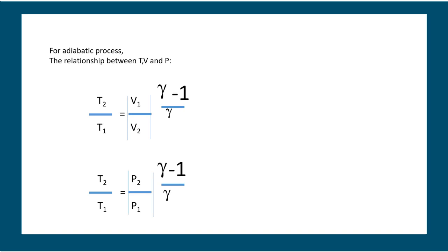Okay, and cp by cv is constant for an ideal gas. This ratio gamma is constant for an ideal gas. Also we have seen Mayer's relationship, cp minus cv equal to r. So using that we can write r equal to cv into gamma minus 1. So we can see that dw equal to pdv, which is equal to cv dt minus cv dt. So the work done in an adiabatic process is given by this equation, dw equal to minus cv dt.